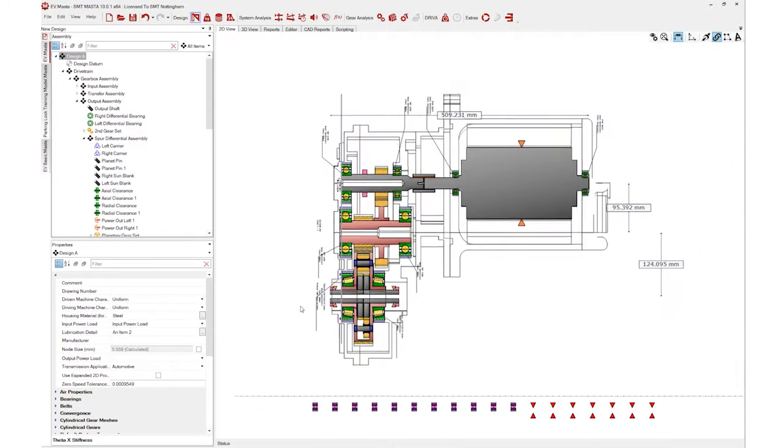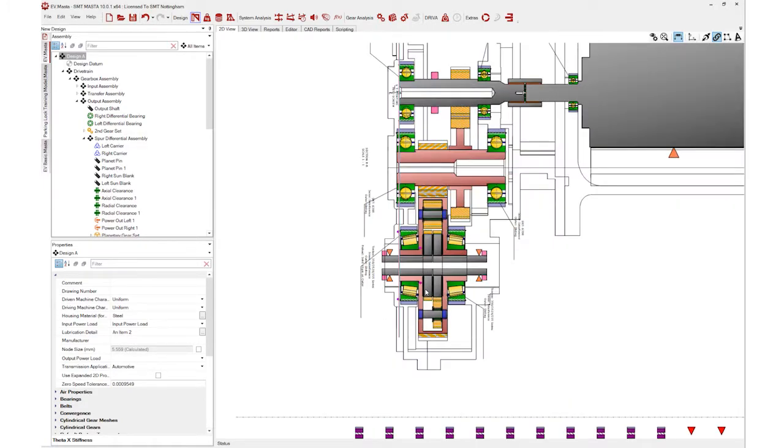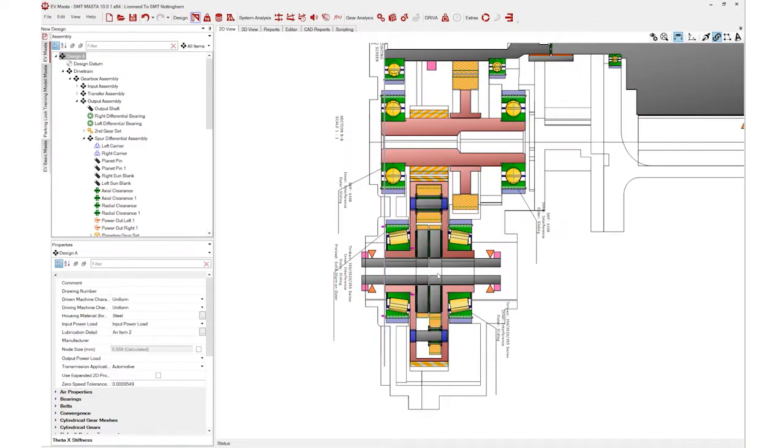for example, chances are there's some point where we're going to have to cut off our master model. We're not going to be able to model the entire rotating inertia as accurately as we may want. We may have to cut the model off to keep it a reasonable size. So in this case, the model's been cut off at the half shafts. In reality, of course, there would be some wheels on the end of here and obviously some more half shaft.